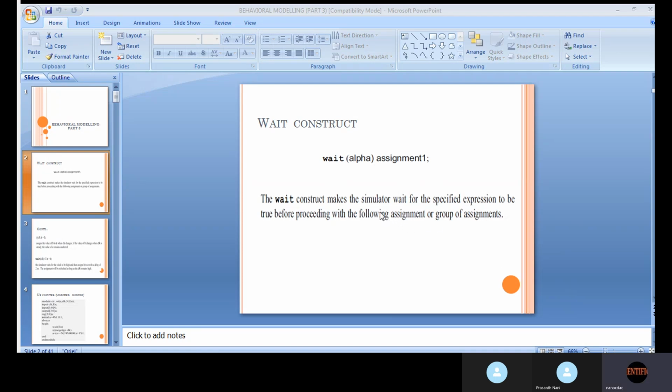ALU 8-bit data flow. Here, what is the error? Are you able to execute this code, Prashant? Carry out Y. You are checking whether f is equal to 3'b000, then a plus b plus carry in, or else if f is equal to 3'b001, a minus b minus carry in, or else if f is equal to 3'b010, you are assigning z to c out and a ampersand b operation you are performing. Else f is equal to 3'b110.